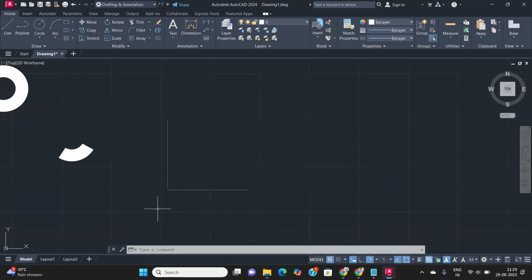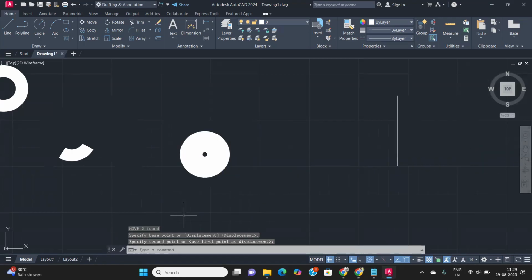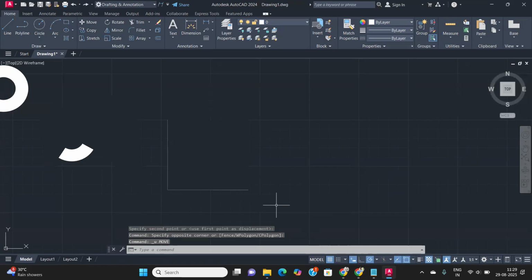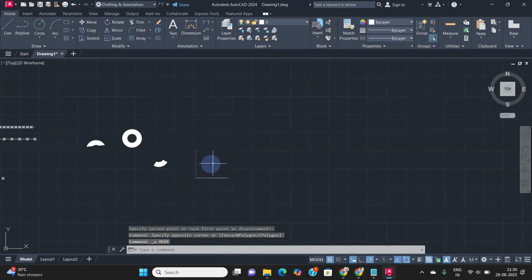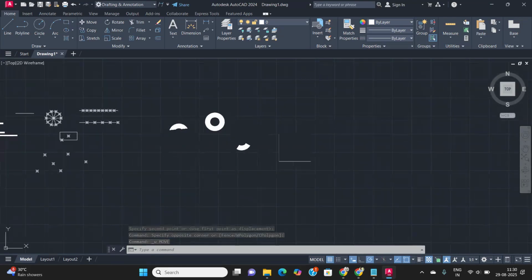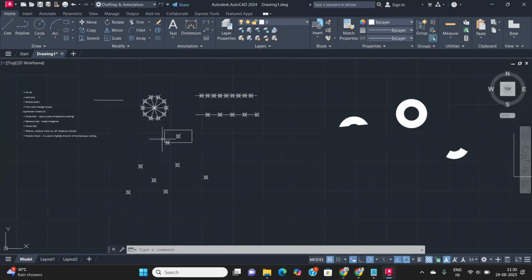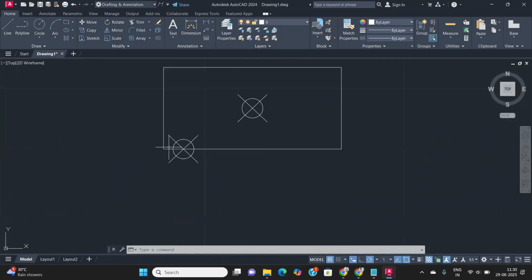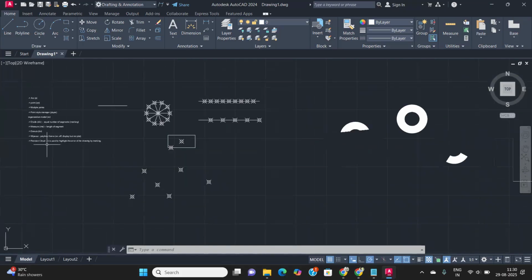Okay, we also call this a wipeout. But your object is still there. If you want to move this part, then this object will be shown. But here I used a wipeout right here, that's why my object is not visible. That's clear. This is the use of the wipeout, for wiping some part. If you don't want others to see this portion, then you can use the wipeout for this purpose, right? Okay.